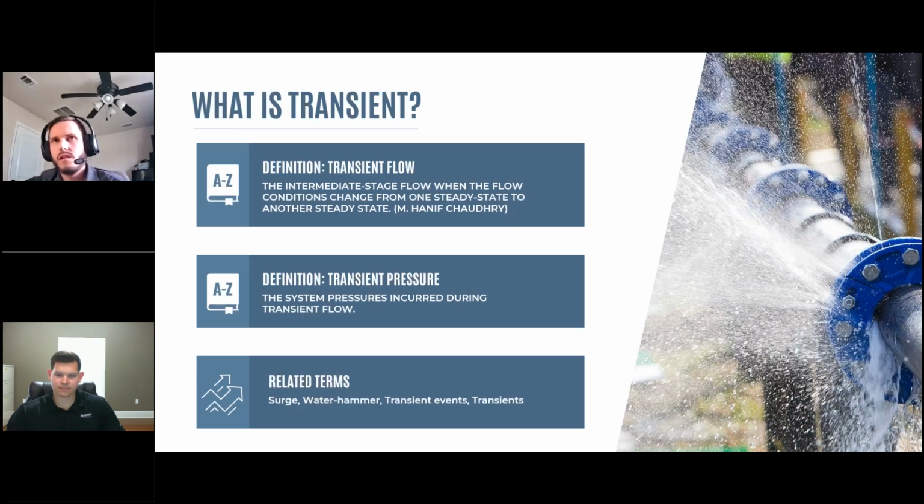So, why are we measuring pressure and not flow? Instantaneous pressure is easy and cheap to measure at high frequency. My coworkers and I even have the equipment installed on our home washing machines. Flow can be measured, but it's not ultimately what we're looking for. It's like an intermediate parameter. Pressure is the parameter that gives us the more useful information.